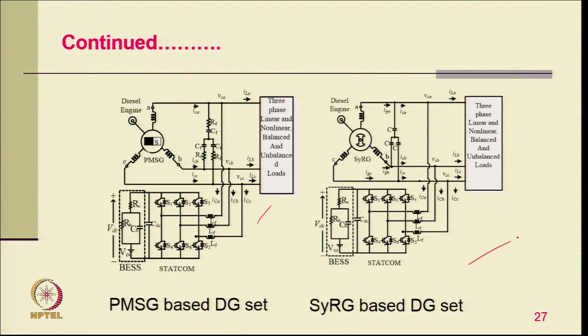So, the battery provides the additional function, you can call it, of power leveling on the generator, so that the fuel efficiency of the DG set can be maintained to the full extent, and the load on the DG set can be maintained between 80 to 100%. However, the load can go even more than 100%, because you can take 100% power from the DG set and more you can take from the battery for a short period, even to meet the peak demand charges or inrush current power requirement of the load.